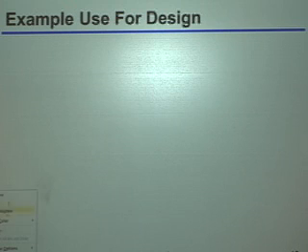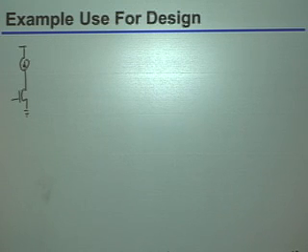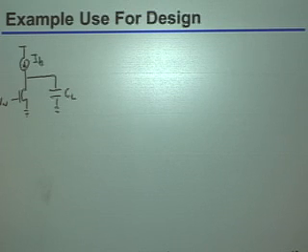Okay? So to keep life simple, let's go with a very simple conceptual amplifier, very similar to the one I drew before. Let's say we have just some NMOS common source amplifier. I'm going to tell you it's driving some fixed capacitive load, and it has some bias current over here. Your job is to pick that bias current such that you meet the overall amplifier specifications, but have the minimum total amount of power consumption.